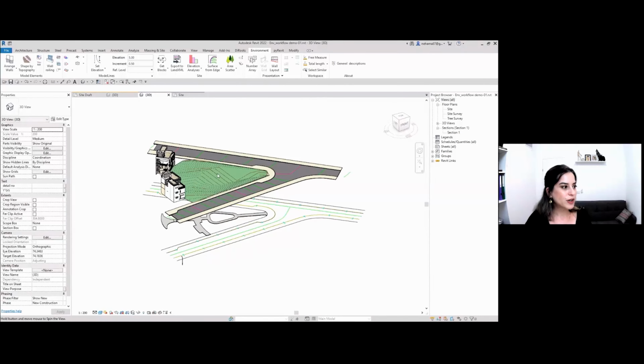They allow us to show and present and manage a lot of information. But Revit walls are meant to go from one building floor to another. So they're meant to go between flat levels. But in landscape architecture, our level is the terrain and it's never flat, it's always amorphic. So to design walls like this, you would actually have to build every section of the wall separately and do the calculations of what you want the elevation to be in each part of the wall.